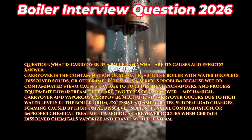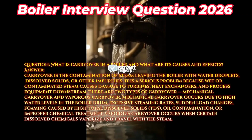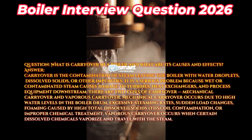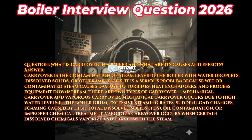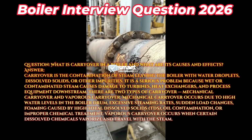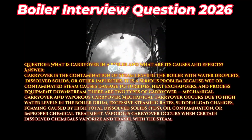Question: what is carryover in a boiler and what are its causes and effects? Answer: carryover is the contamination of steam leaving the boiler with water droplets, dissolved solids, or other impurities. It is a serious problem because wet or contaminated steam causes damage to turbines, heat exchangers, and process equipment downstream. There are two types of carryover: mechanical carryover and vaporous carryover.